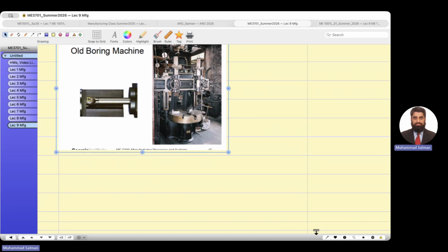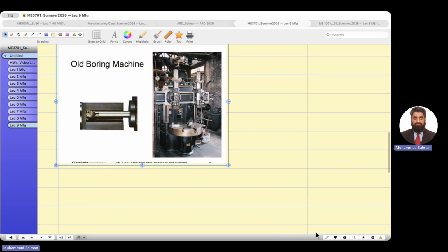You see, this tip, we call this an insert. This is the whole workpiece, the tool, it has an insert. We call this tool inserts. These inserts could be having sharp edges, 1 2 3 4, and this is an Allen screw. Usually we have an Allen screw, and then the tool holder, where we put this insert inside. So once one edge is blunt, you can use the other edge, third edge, fourth edge.